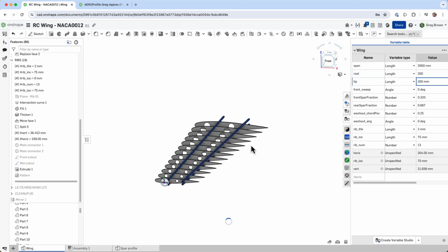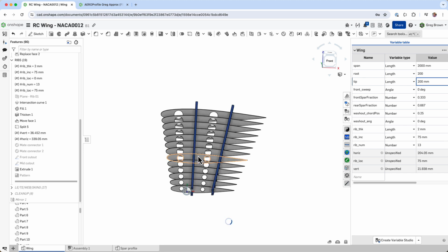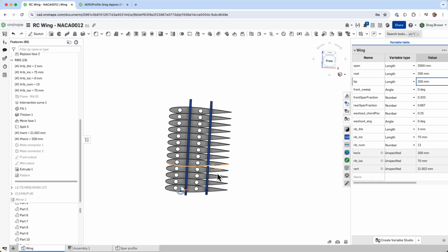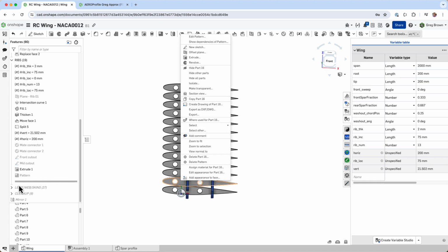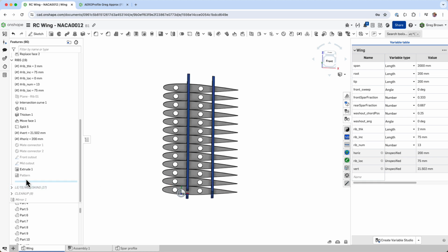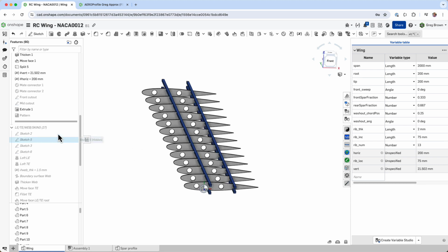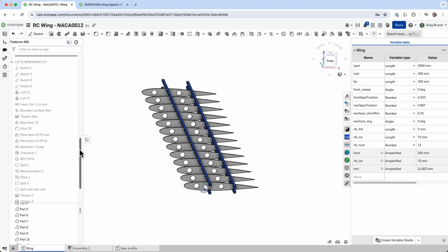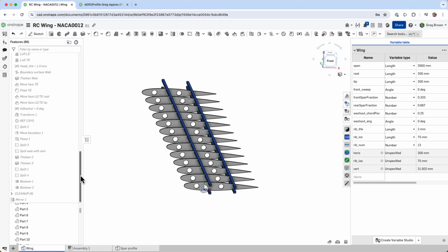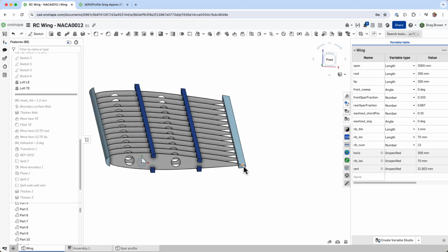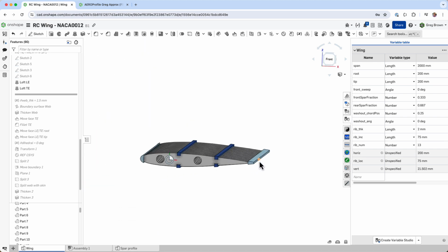One of the designs I have, my glider design, actually has a uniform section through it. It's just swept back, and we can recreate that later on. The next block, functionally, is this leading edge, the web trailing edge, the skins over the top, and the web at the front. I think that is essentially the same. I'm still using a loft feature to overbuild what is going to be the trailing edge.